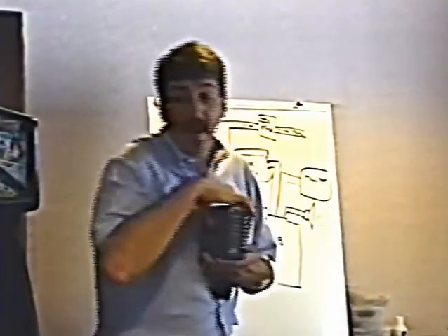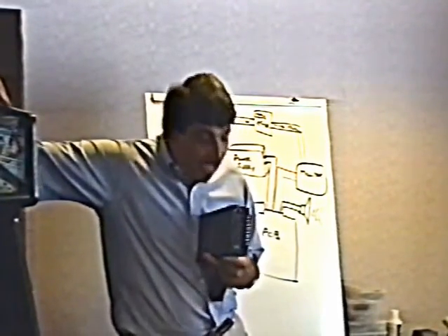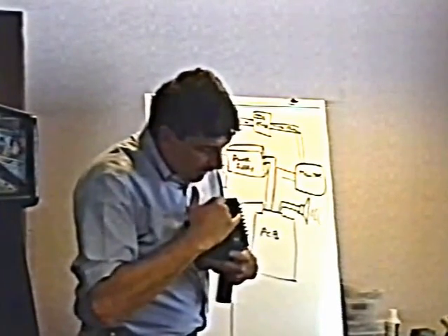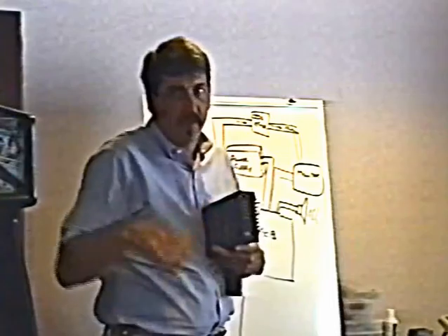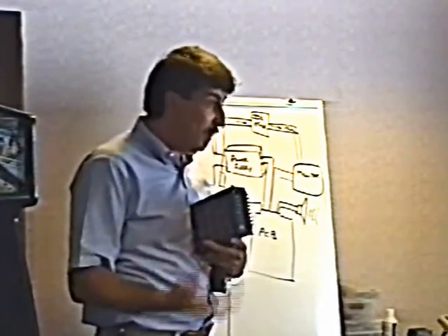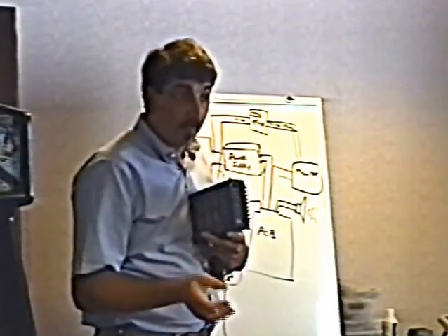so you get to the game and you coin it up, it doesn't do anything. You've got to assume your power supply is crapped out. And the easiest thing to do is you put your black meter lead on ground, the red meter lead on plus 5, and with the game turned on and powered up, you should read 5 volts DC there. If you don't have your 5 volts DC there, there's nothing coming out of the power supply.